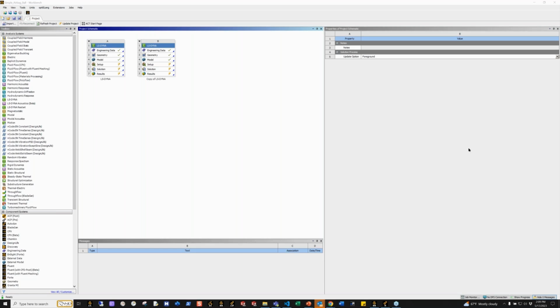If you buy Ansys Mechanical, say for example an Enterprise or Premium license, you do get an explicit dynamics package, but LS-DYNA is a far better and honestly a far more developed explicit code. So why do you need an explicit code? Because there are problems you simply cannot do inside implicit.